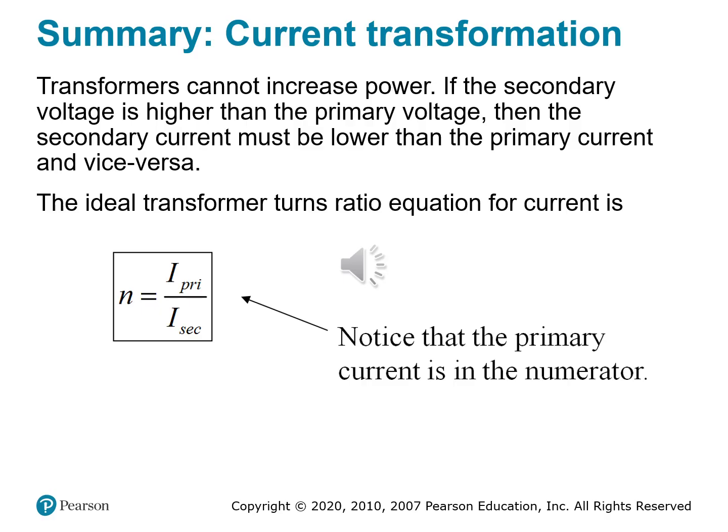It also matters in audio amplifiers and signal transformers, where matching impedance also means matching current behavior. Just remember that voltage and current are inversely related in transformer operation. The product of voltage and current, which is power, stays roughly the same. And this balance is what makes transformers so effective and why you must consider both voltage and current when designing or analyzing them.